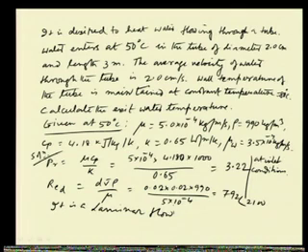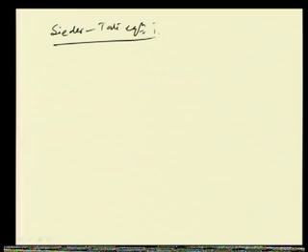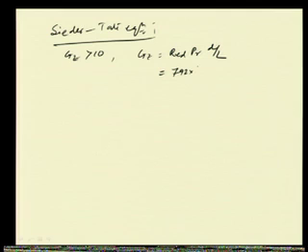So, when it is a laminar flow, we will try to use the Sieder-Tate equation. But when we use the Sieder-Tate equation, we have to check whether the Graetz number is greater than 10 or not. The Graetz number is Reynolds into Prandtl into d by L, and if we put the values, 792 into 3.22 into 0.02 by 3, it becomes 17, which is greater than 10. So, the Sieder-Tate equation is applicable.